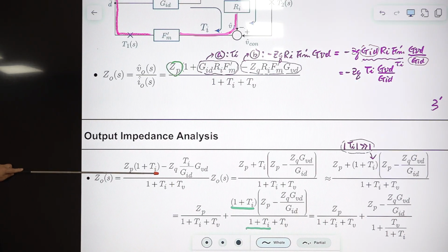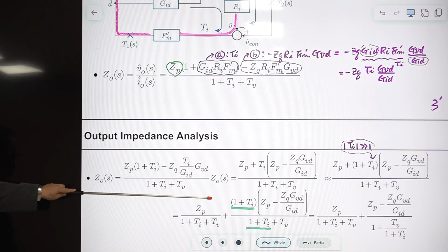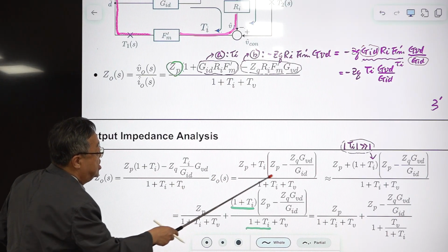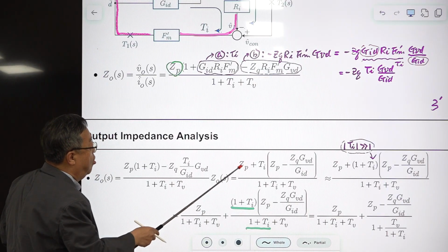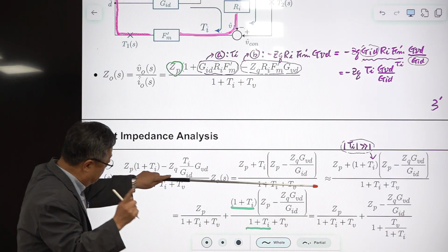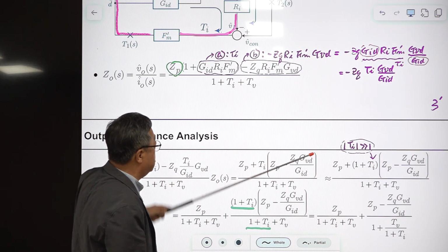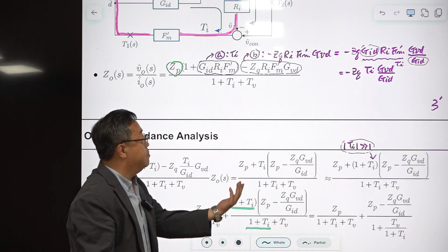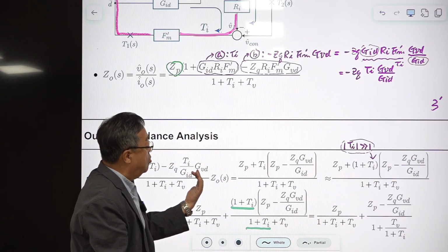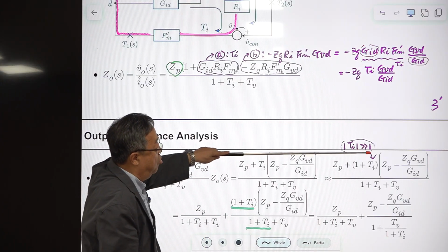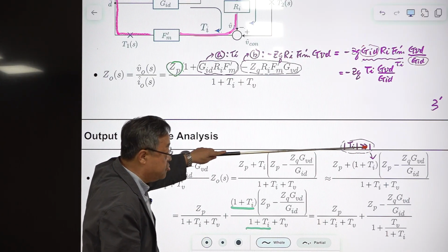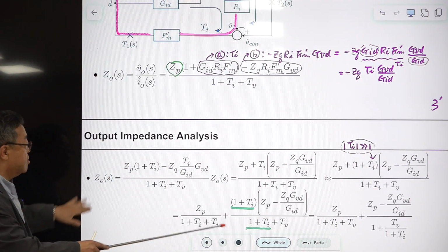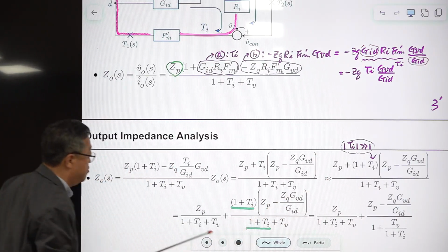Okay, Ti is the current loop gain, and this is the same expression. We split it into the term having Ti in front and the term without Ti. One very critical, very important approximation is that we replace Ti with 1 plus Ti, because before the loop gain crossover frequency of the current loop, the magnitude of Ti is much larger than unity. So adding 1 is nothing. Then you separate this part, and we have this.